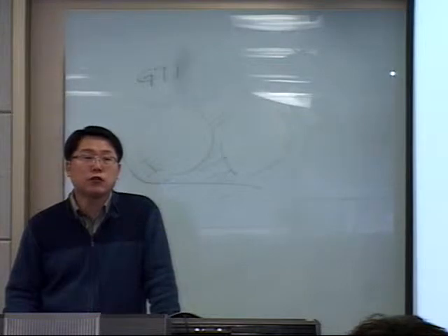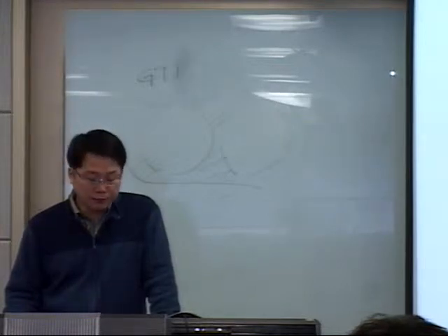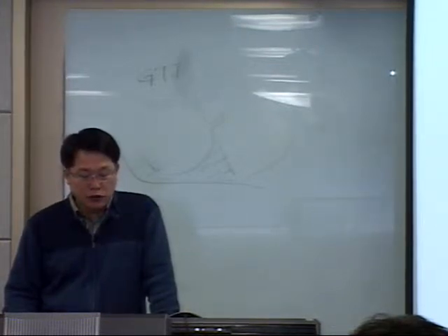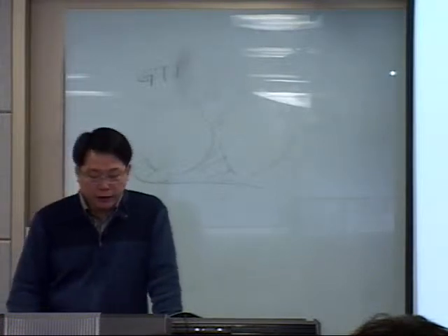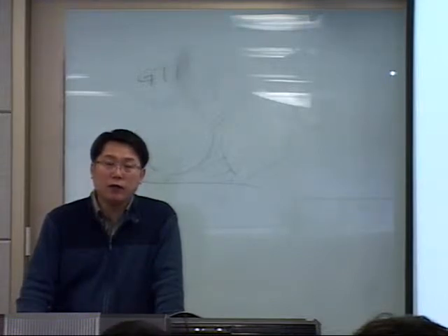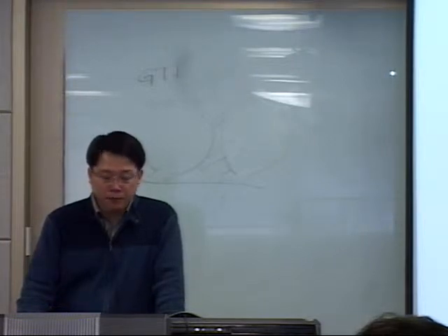High pressure protection has two layers. One is if the pressure is high, BOG should be removed from the tanks, and the BOG is supposed to be liquefied in the reliquefaction system and returned to cargo tank.